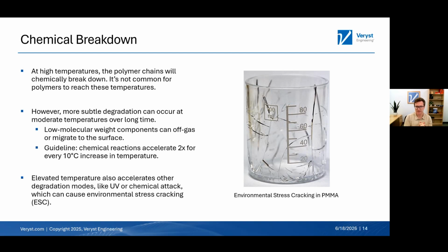And so you can weigh how much temperature budget you can have in your accelerated life test versus your material structure and what you actually need to verify about these different properties over time, to design an accelerated life testing protocol that will give you some information about how the properties of your material are actually going to change under that long life in the field.